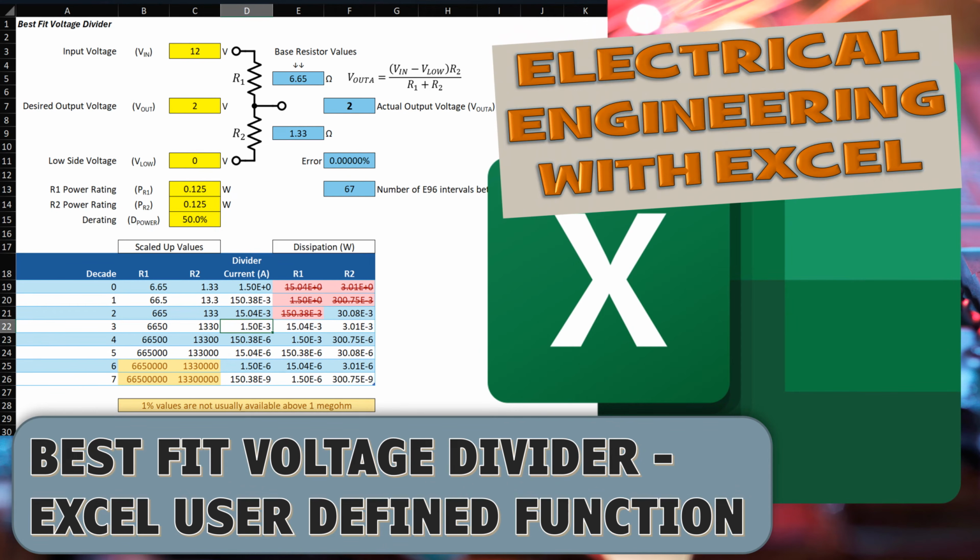In this video, we will look at some Visual Basic for Applications user-defined code in Excel to select the best fit resistor values for a voltage divider. This is only for the selection of 1% tolerance resistors. Although 1% tolerance is good, arbitrary selection of values can result in the divider's output being less precise than it could be. Let me show you an example.